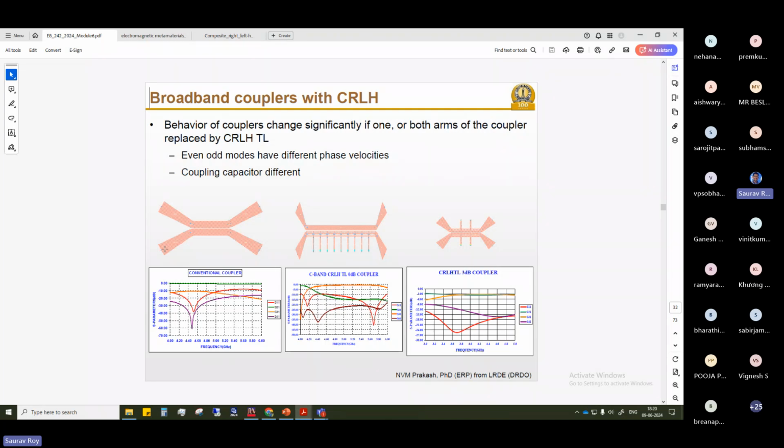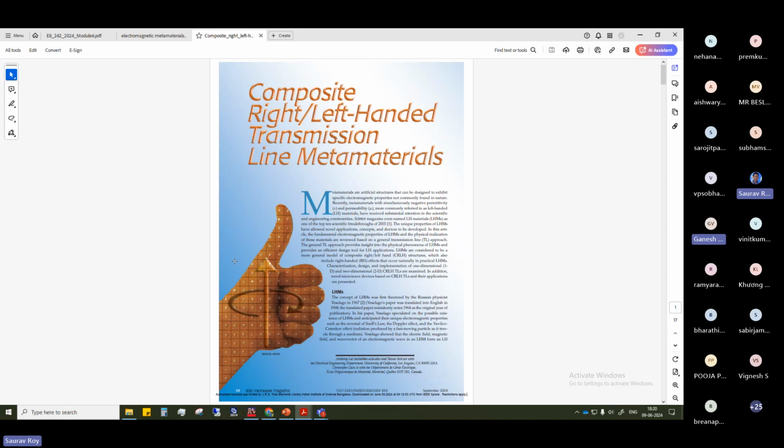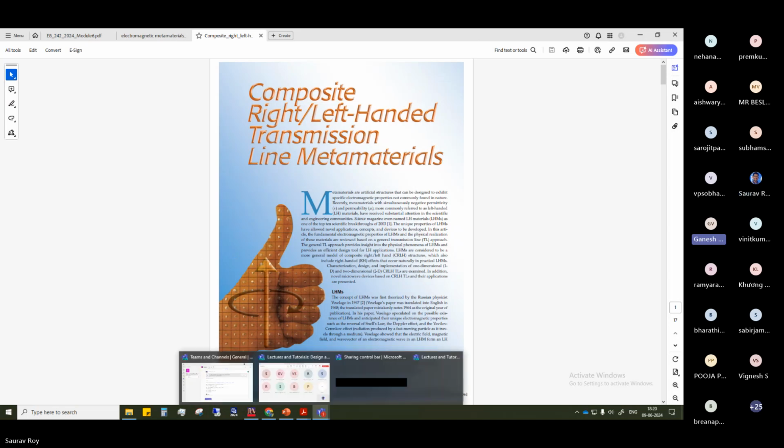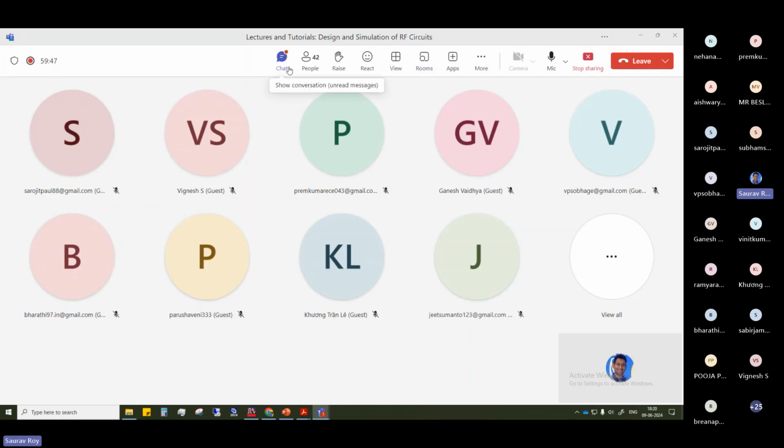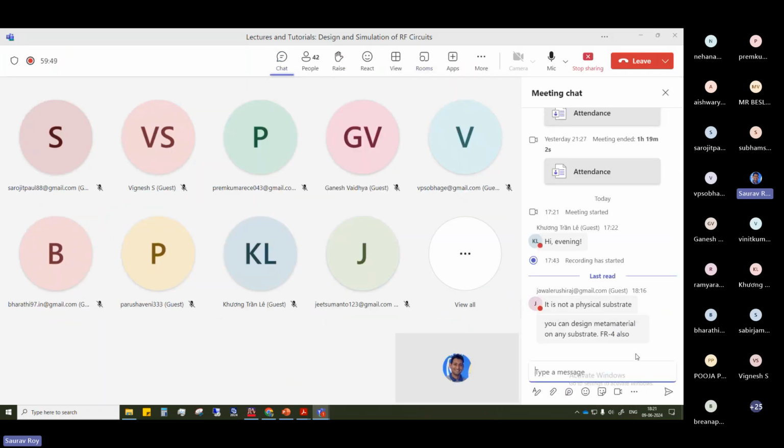It depends on the substrate and the permittivity or permeability properties. All substrates come with a plot. If you look into the data sheets, they give the behaviors with frequency, and you can also find the power values in the data sheet itself. Usually it will be in milliwatts. Whether it will be in watts, around 300, 400 watts, is it possible to do? Yes. Whatever you have in a normal microstrip line, the same you can do here also.